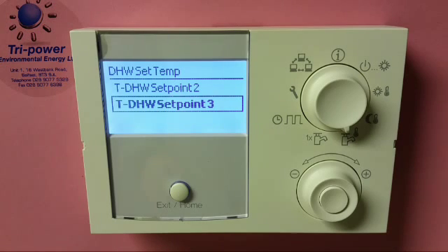The beauty about this is that if the boiler has collected solar and it's up past that temperature, even though you have programmed the system to be on, the boiler will look at the temperature inside the cylinder, whether it's a 300 or a 500 litre cylinder, and actually ignore the settings because the temperature is already inside the boiler. If it happens to drop below that because you're using hot water, during the time clock period, it will bring it back up again for you.